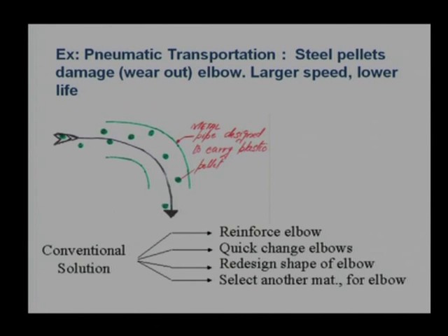So, we need to think about which material will give a good result. From a conventional point of view, or simply without much knowledge, you can say we can reinforce the elbow. Reinforce means we can provide some sort of rubber padding inside the elbow that will sustain or absorb the impact. However, the question is, will that be a good solution for us? First, we need to change the elbow and coat it. Is it simple or easier? If it is easier without much cost, then we should go ahead with that. However, we find that it is slightly difficult.